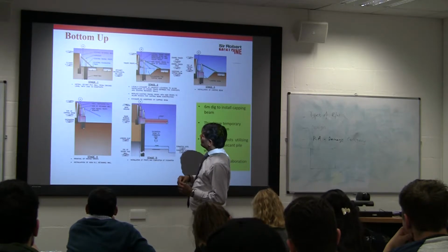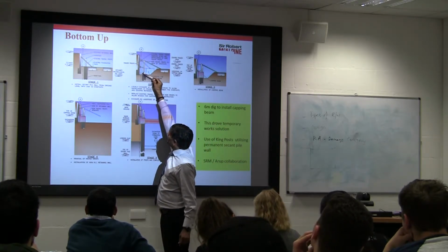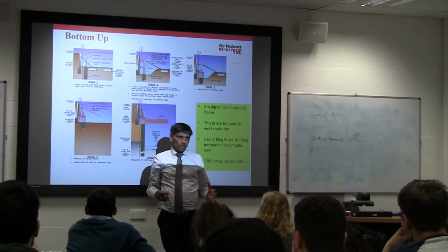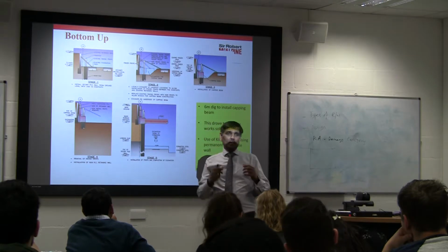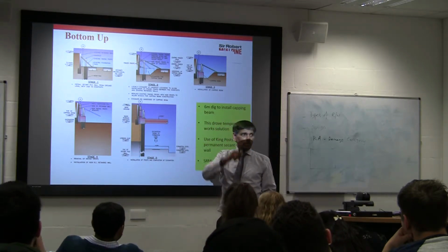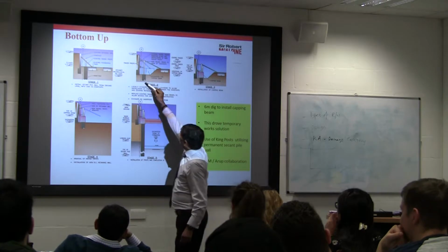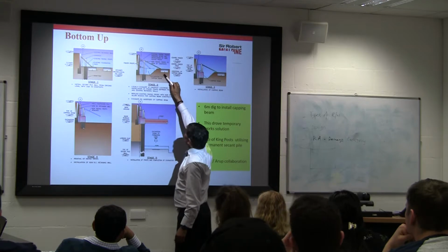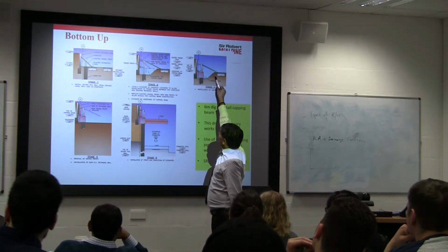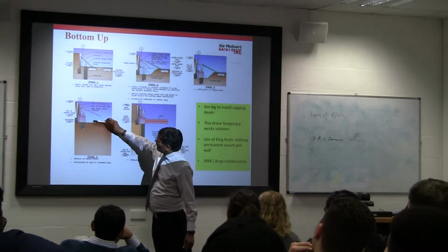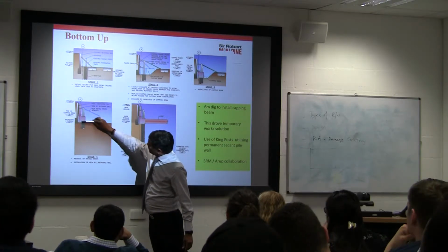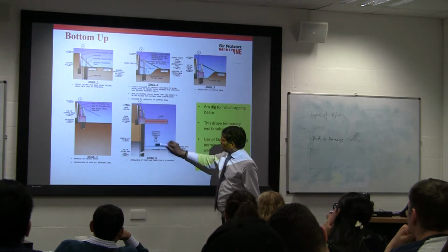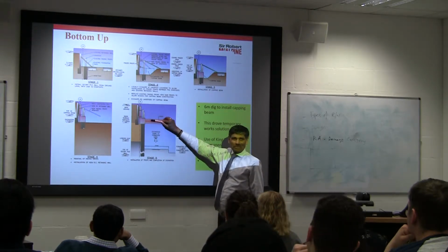So the way to do it is to obviously go a minimum distance, do the secant piles here, and then in the secant piles we put what is called a plunge column. So it's basically when the concrete is done, you drop a steel post inside it, and that will hold the existing wall. And then start digging, as you can see here. The next sequence is to hold that to a thrust block that is grounded, and then when you dig, now that is cantilevering, you construct the capping beam as we discussed. Now we are dropping the ground from there, straight after you install the prop. Yeah? See what I'm saying?